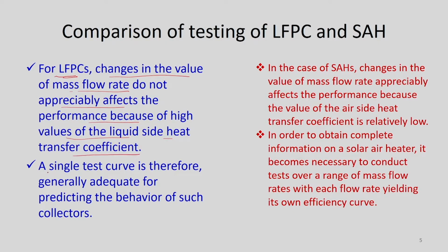That is why a single test curve is generally adequate for predicting the behavior of such collectors. But in case of solar air heaters, the changes in the value of mass flow rate appreciably affect the performance, because the value of air side heat transfer coefficient is relatively low. This is the primary reason.